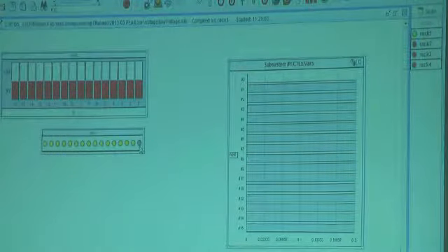You have to be careful a bit because channel 1 here is on the left side, but it's the least significant bit, so it's on the right side in runtime. So again, if I change it to channel 5, the channel 5 light goes off.